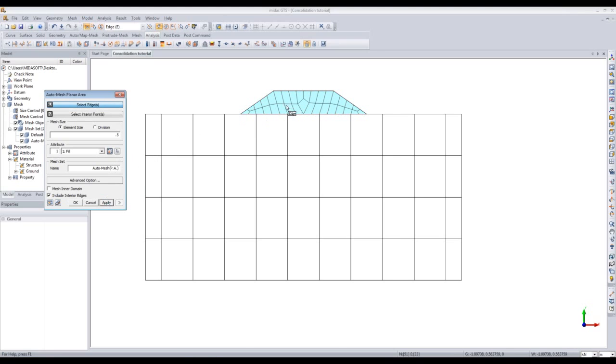Okay, perfect. So not exactly what I wanted. It probably could have stood to be a little more fine. If I had made it 0.4 or 0.3, it would have been more fine. But just in the interest of time, I'll move forward and do the meshing for these sections over here.